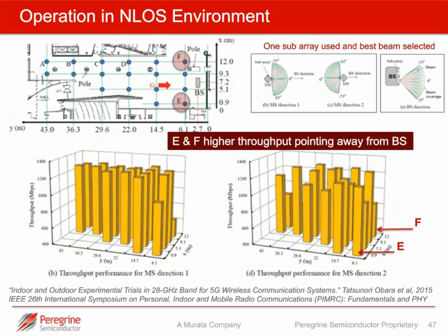And the reason that this is most likely occurring in these two cases is they have obscured views, so they need a reflection to get a strong signal, and it may also be influenced by the fact that with anything coming directly, there are multiple signals arriving around the same time in the direct path case, causing more intersymbol interference. So again, this makes it important to be able to select the direction of the signal that we receive.